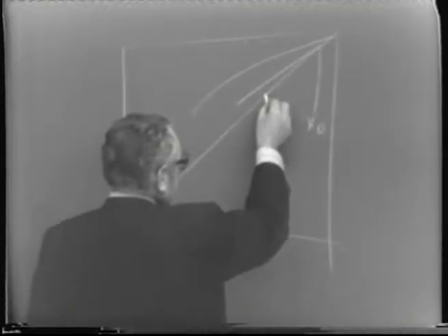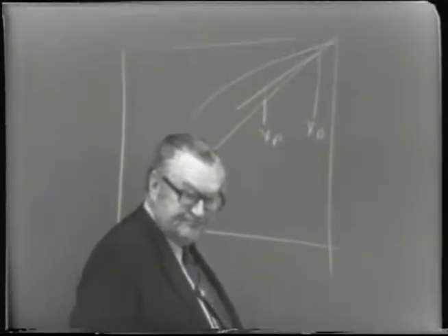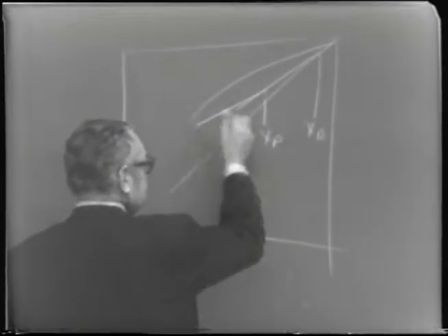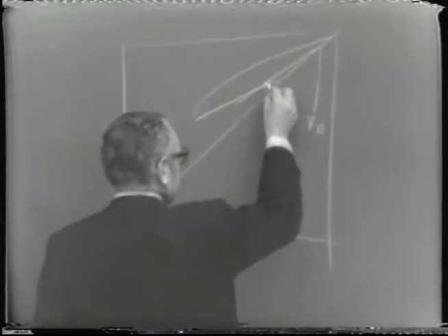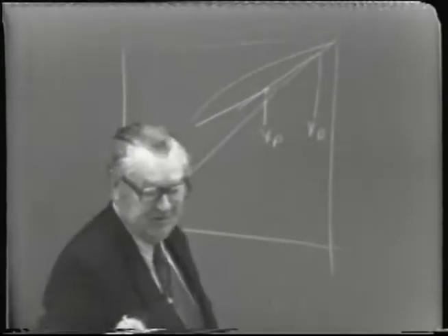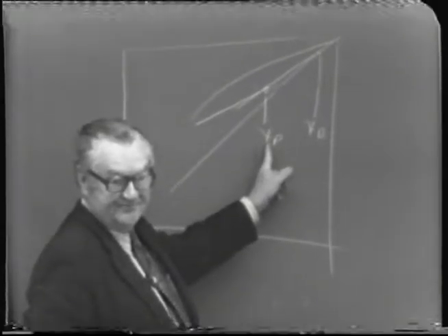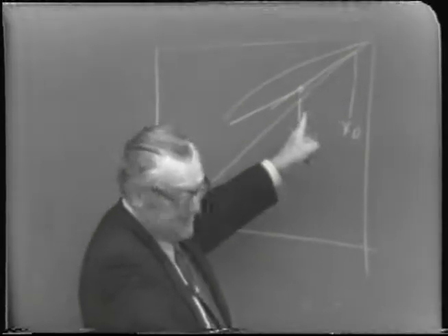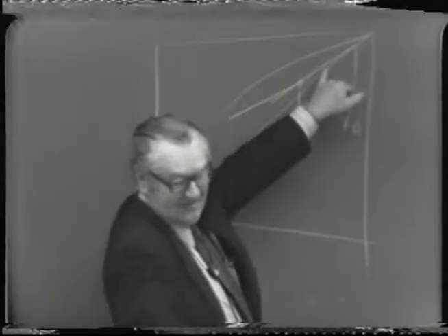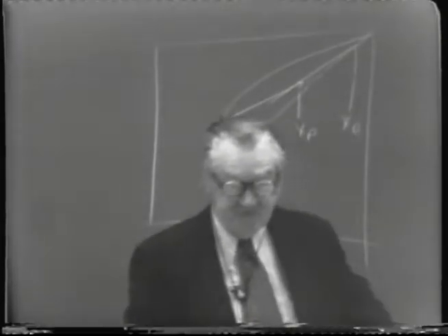And then at this point, we change the slope by taking out more of a liquid side stream. Why then, at that point, the slope changes. In other words, the slopes of the two separate operating lines, if you want to consider it as two separate operating lines, intersect at the side stream composition. So that's what we've done here, but it's not so obvious. This is a slope of 0.99. It doesn't show up as being separate from the diagonal.